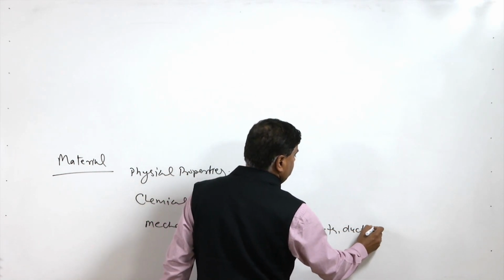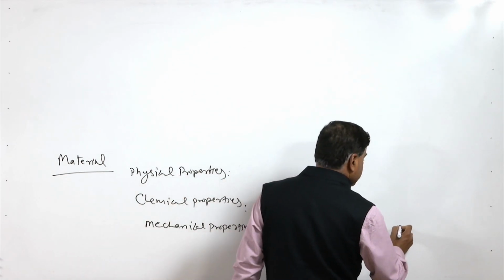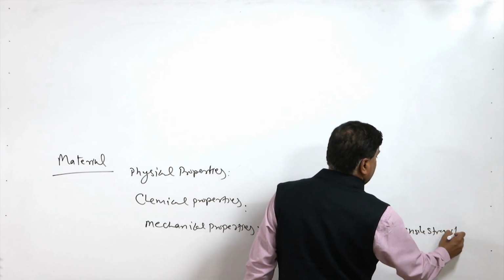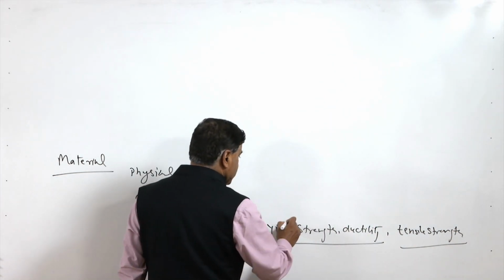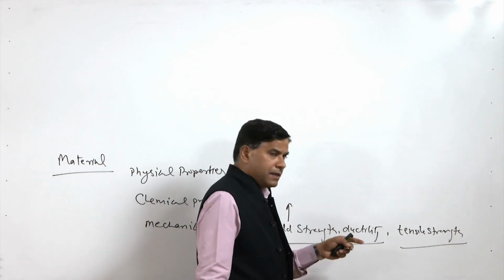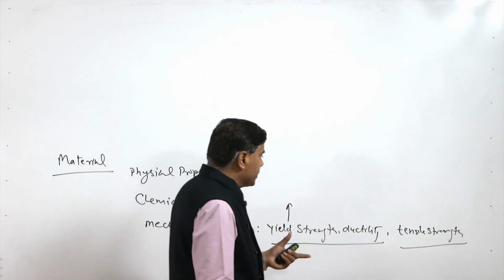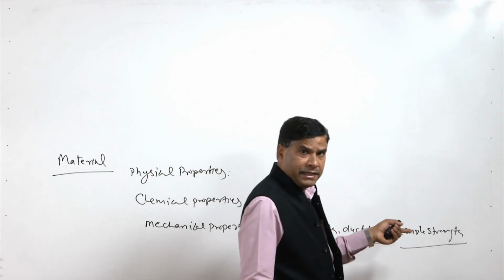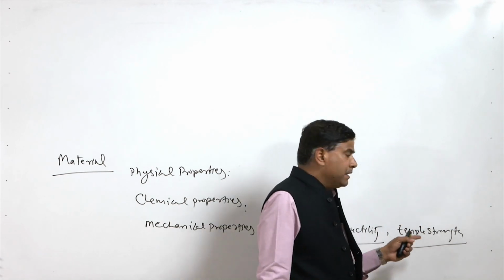ductility. These are the two important properties, and maybe sometimes tensile strength or ultimate tensile strength also affects the manufacturing aspects. So, here yield strength is the stress level where the plastic deformation starts. The elongation is the extent of the deformation or strain which a material can sustain prior to fracture, and it is measured in terms of percentage elongation, and also the percentage reduction in area is another parameter used as a measure of ductility.